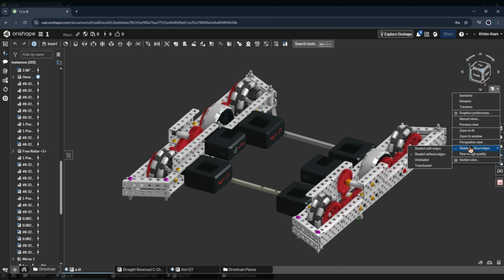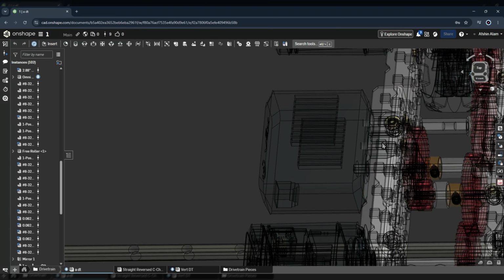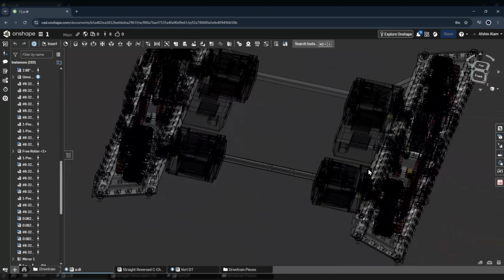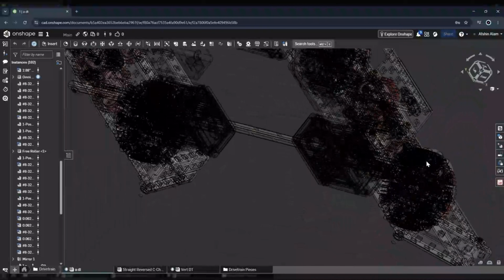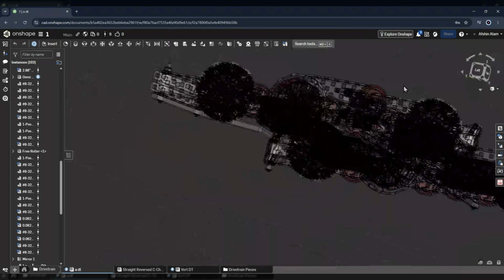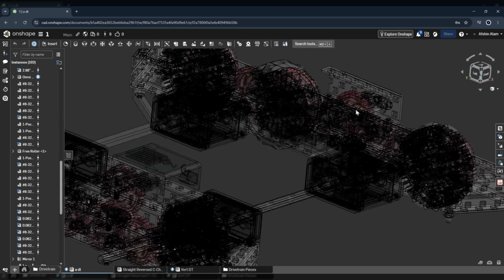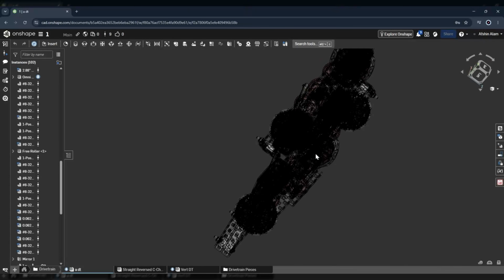And then the further that you go down with these, the lower quality it gets, but the faster times you'll load. So sometimes when I'm loading huge CADs, I'll switch to translucent, and as long as you generally know what you're looking for and what you're looking at, then it's not that bad maneuvering around. I recommend not doing this though, unless you've CADed for a while. But this is one of the few things that you can do to increase loading speeds by a bunch. So right now there's no input delay at all.